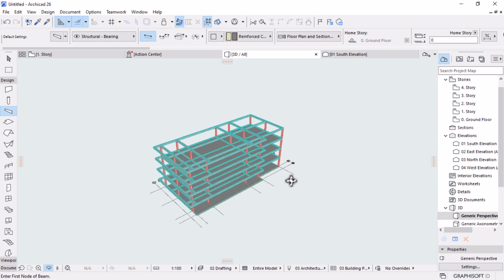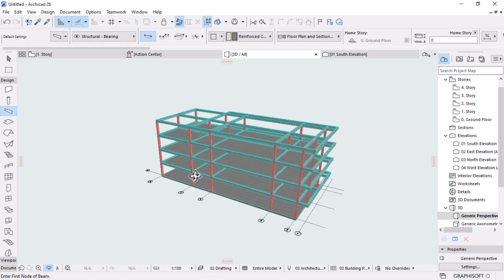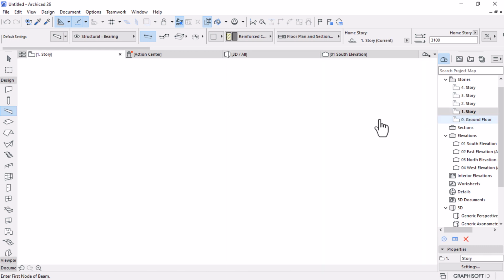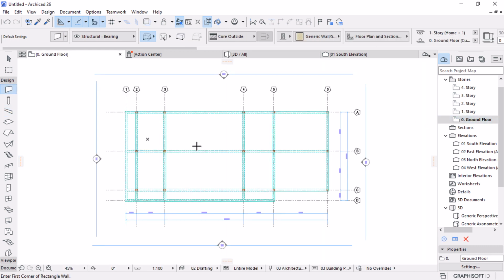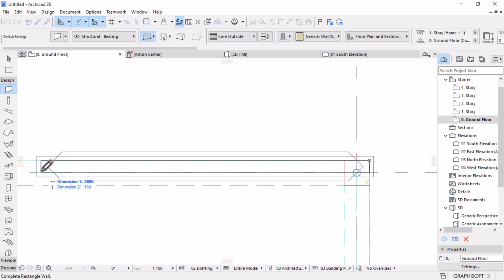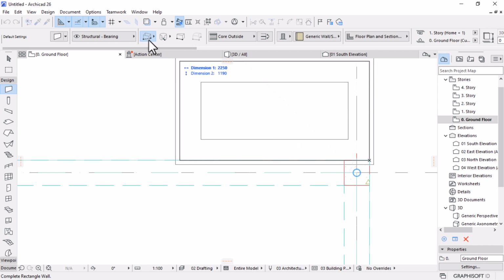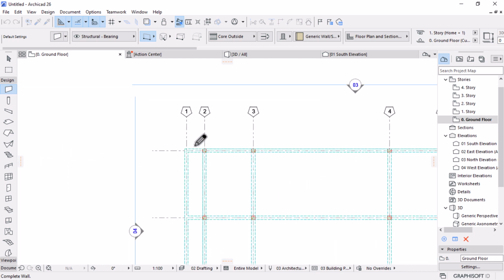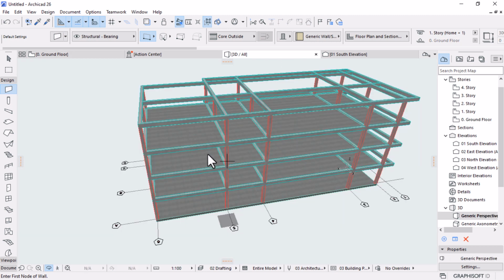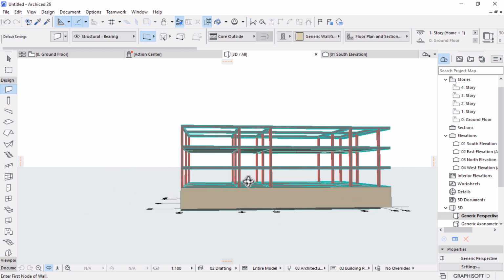Okay, so from here we now need to close this off. We'd have a wall that will come all the way to there. So let's go here underground and activate that wall. This wall is going to sit right in the middle of this. I could decide to make my walls go outside the structural elements, and then let's change the geometry method to this one for placement of this wall, and then I'll just draw a wall from there to there. There we go. So if we check on 3D, that's basically what we have.